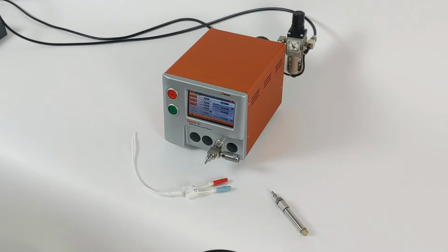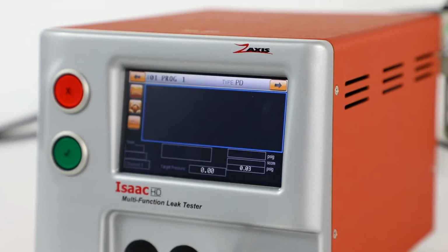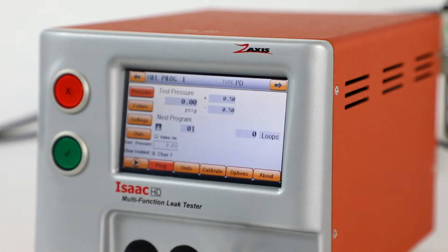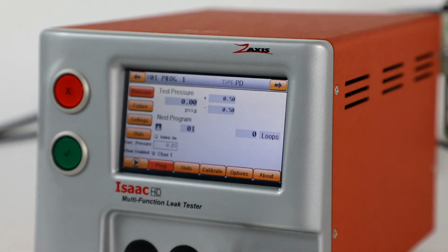We have a simple catheter device today that we'll set up from the beginning. From power up, we'll go to the program menu by hitting the Gears button. The Gears button goes right to the pressure screen. We're going to fill in as much of this information as we have. Some of it we'll guesstimate, and we can go back and forth from the run screen testing it to see what happens. This particular application calls for a 10 psi test pressure.